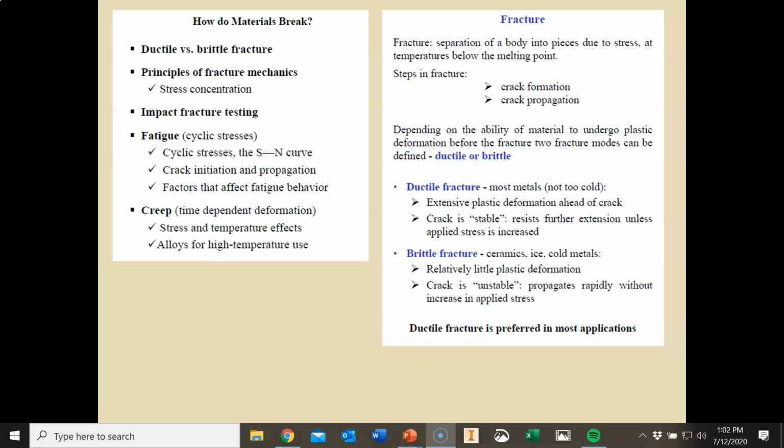In brittle crystalline materials, fractures can occur by cleavage as a result of a tensile stress acting normal to crystallographic planes with low bonding, in other words, cleavage planes. In amorphous solids, by contrast, the lack of crystalline structure results in conchoidal fracture, with cracks proceeding normal to the applied tension. In a brittle fracture, cracks run close to perpendicular to the applied stress.